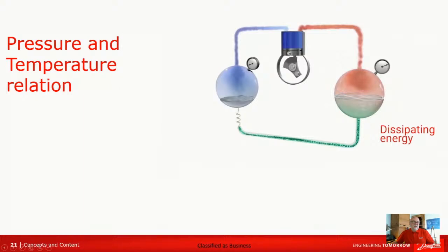Receiver in the cycle, yeah, no, that's a good question. Yes and no. Actually, you have a receiver also in the liquid line itself, but now we're talking about small, very small systems. In larger systems, yes, you will need a receiver, definitely, to be able to have a higher dynamic, so to speak, so that the system can work under more different loads.